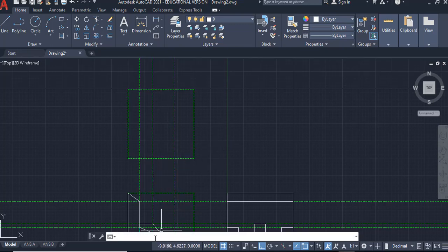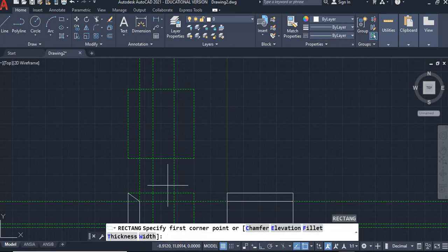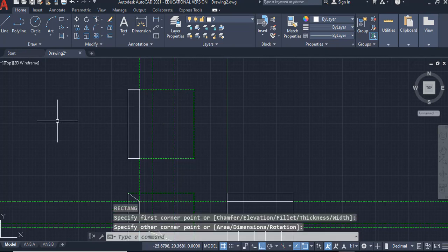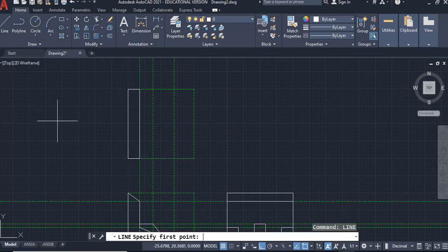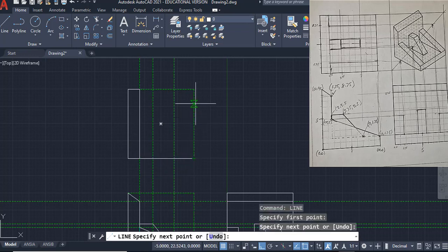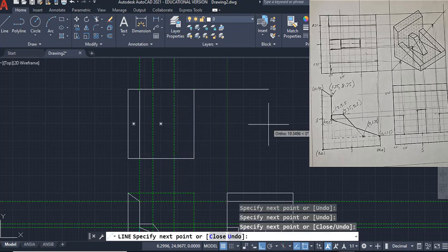As you're drawing, try not to draw a bunch of line segments over the top of each other. So rather than doing an entire box and then another box over the top, if you have two lines on top of one another, that makes it extremely difficult to extrude when we get into 3 dimensions. So be very careful that you're not drawing one line on top of another line, and it'll make 3D work so much easier. So for this next box, I'm not going to make another rectangle because that would draw another line on top. I'm actually going to walk around the base of this.